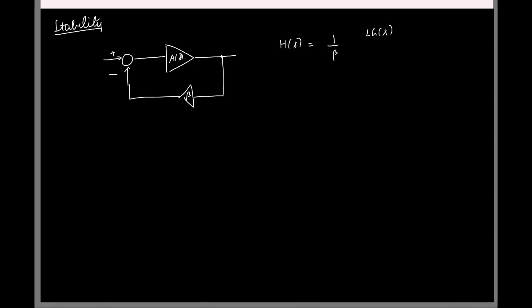and this is the classic negative feedback model we were looking at. And of course we know the closed loop transfer function is 1 by beta times the loop gain by 1 plus loop gain, right? And the loop gain itself is beta times P of S, right?